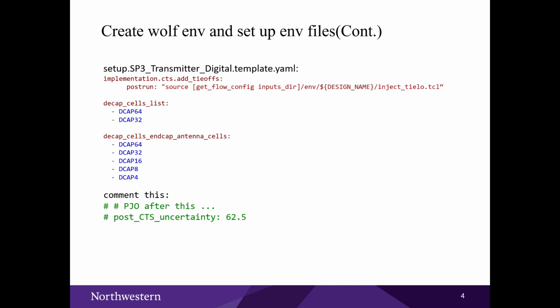And the second thing we need to change is the decap cells, because we use RVT and the default decap cells are LVT, so we need to change that. And the third thing is that we need to comment out the post-CTS uncertainty.